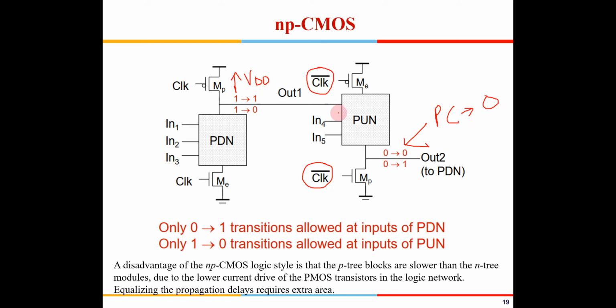So you don't have that issue of cascading out here. What happens to this node? Either it remains 1 or it can go to 0, right? These are the two conditions which can happen. Suppose this is 1. What happens, right? This is a pull up network, right? So this continues to remain off out here, because a 1 will keep the PMOS off. So this will continue to remain 0. So there is no issue. Suppose it is going from 1 to 0. If it is going 1 to 0, in that case this will be switched on, and then this will go from 0 to 1 here. So there are no issues out here, right?